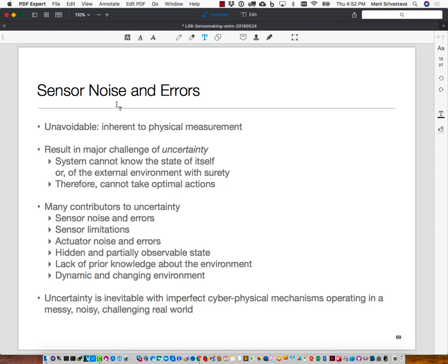I take repeated measurements, I'll get some sort of a normal distribution. But that's not the only type of error that you may encounter with sensors. Sensors also have bias. That is, they may give you a reading which just has a shift in it. So that's a different kind of error. All the readings are just shifted by a certain amount, some delta. So it's an offset there.